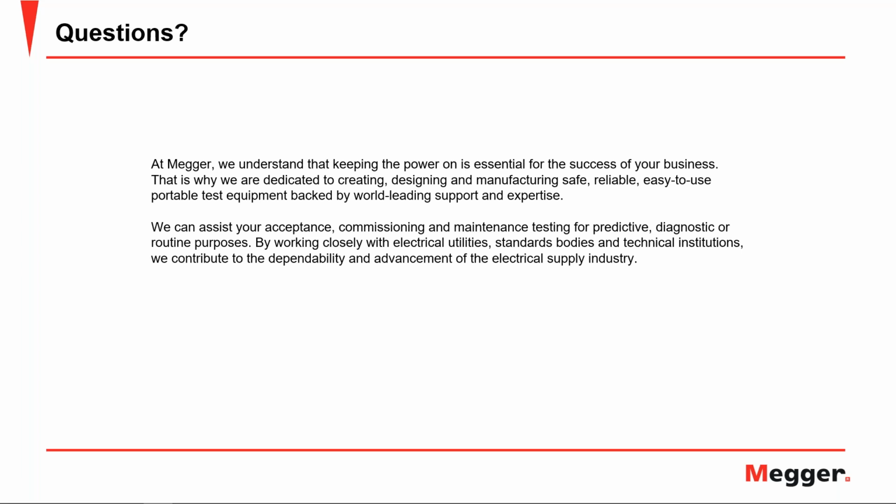I would say it is valid, yes, but if it is a critical system, I personally would rather test it at the full rated capability, whatever the setting is for service. I would advocate to test the breaker at that setting, depending on the criticality of the system it's protecting. And I don't know if Jason wants to add something.